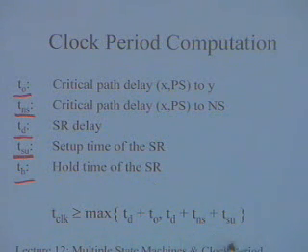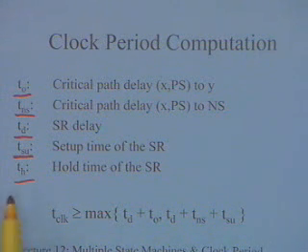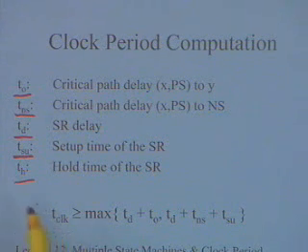Hold time actually does not come directly into this picture. If the hold time is very large, it comes in some other form, but typically the hold time is much smaller, so it doesn't contribute to this. But it does contribute to the fact that you have to design your input in such a manner that it follows that hold time logic.